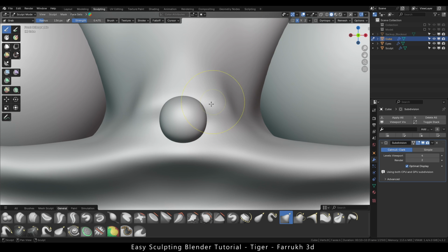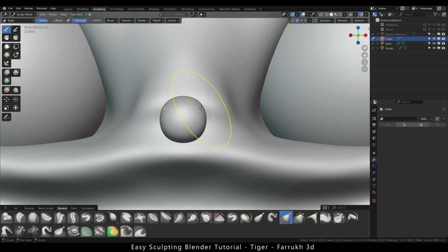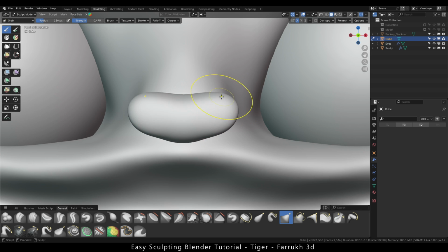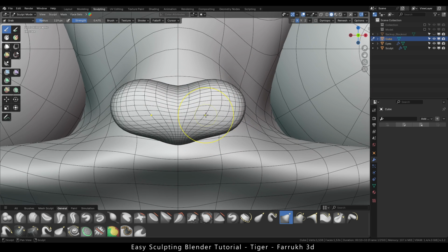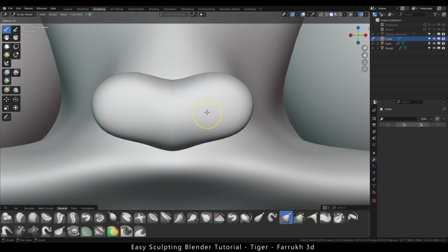In the sculpt mode, turn on X symmetry. If we sculpt the shape, you may notice some problem in sculpting. It may feel slow and lagging. The reason for this is that we have not applied the subdivision modifier. So it's always good to apply the subdivision modifier in case the base object is low resolution, like here it was just a cube. Make the nose shape wider.